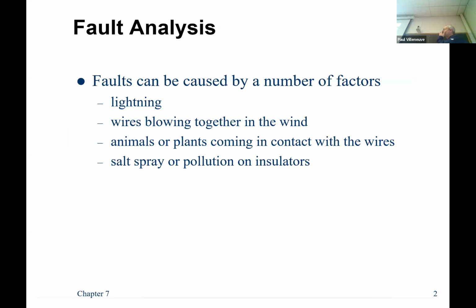So where do you get faults? Lightning is one. It's not that common to get faults from lightning. Normally you have overhead ground conductors that provide some path to ground. You also have lightning arresters, so if a wire gets hit by lightning, you have a surge arrestor, or lightning arrestor, that's the same terminology, that will shunt any excess voltage as long as it's not overloaded.